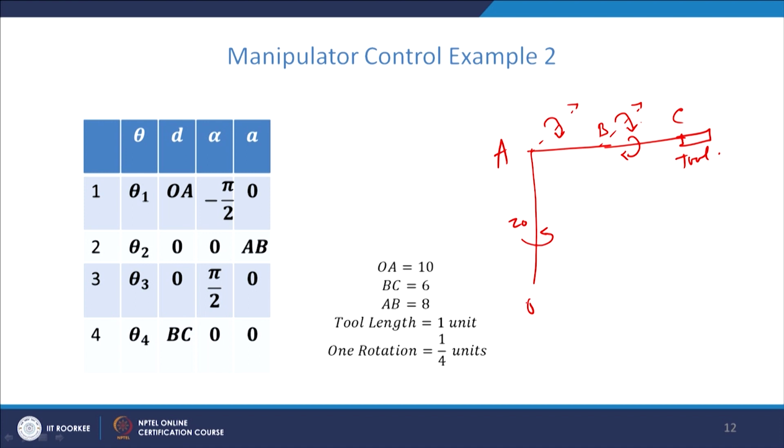So, here OA is given by this expression, this is a joint distance, and similarly BC is a joint distance, AB is the link length, according to the parameters theta 1, theta 2, theta 3, theta 4, these are the joint angles. So, with adjustment of these 4 angles, one can perform a desired task using the robot manipulator.